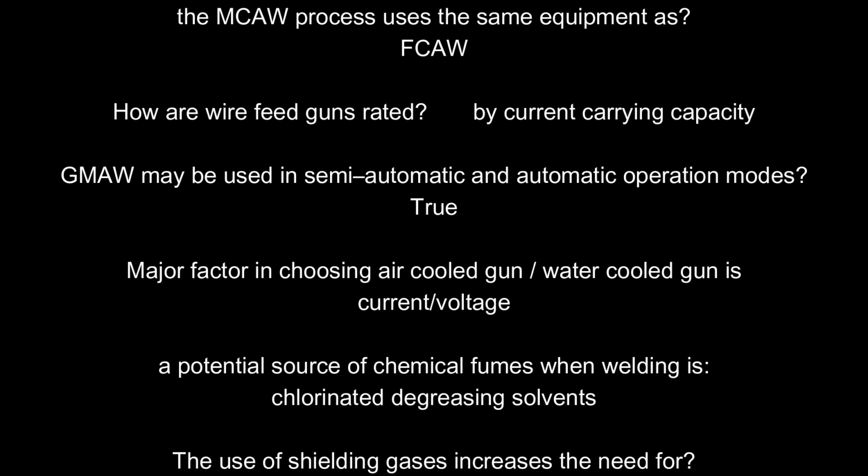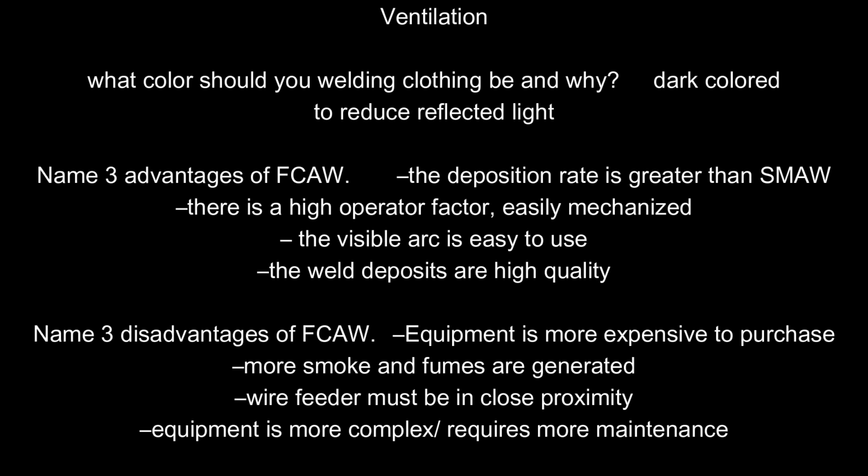A potential source of chemical fumes when welding is chlorinated degreasing solvents. The use of shielding gases increases the need for ventilation. What color should your welding clothing be and why? Dark colored, to reduce reflected light.